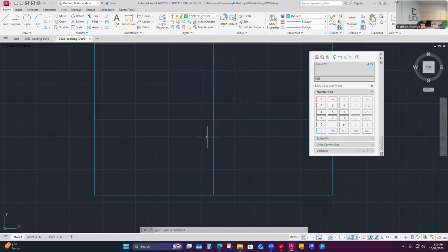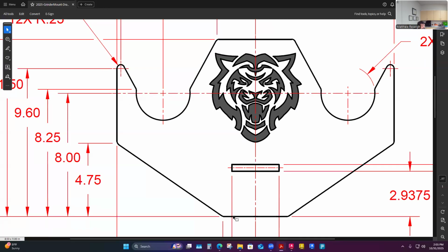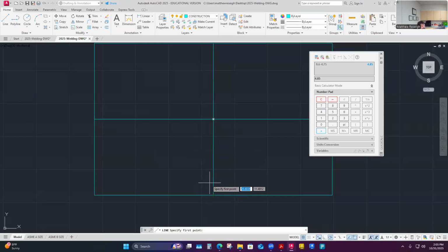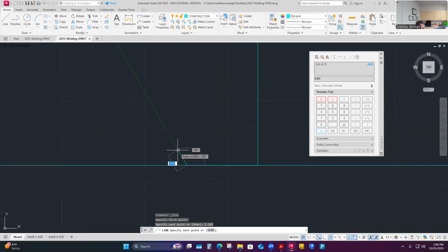If you forgot to change the line layer, and you went in here to do that, let me look at it real quick. This 2 1/8 long line starts right here. I'm in the line command, left clicking right here, drawing this over. I'm going to enter 2.125 as the line length, and then hit enter. It drew that line, that's where it ends, and it's ready to draw again. I'm going to hit enter again to escape the command.